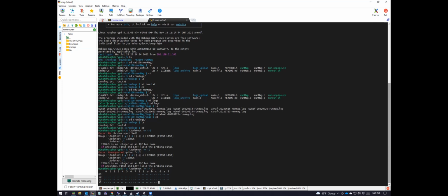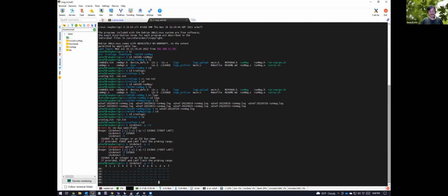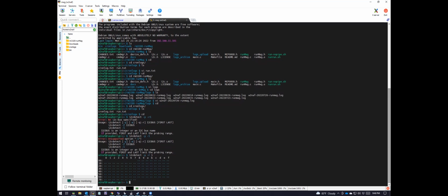Your bus isn't shorted, but it's not seeing anything. So nobody's talking, and you should, let's see, do you have a temperature sensor at the local end? I guess so. I don't know. If yours does, you should be seeing it. Which board are you using, Nathaniel? I don't see the local end. You should see 3 devices normally: a local temperature, a remote temperature, and a remote magnetometer.